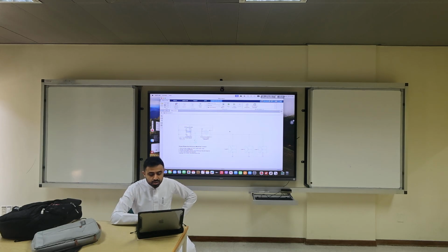Okay. So if you go and open the exciter, and this is homework 2, I will ask you to read about this synchronous machine AC1C. So here what you can see, we have signal 1. This is a terminal voltage. This one is what? Unit delay, 1 over Z. You remember 1 over Z? This is just a delay.